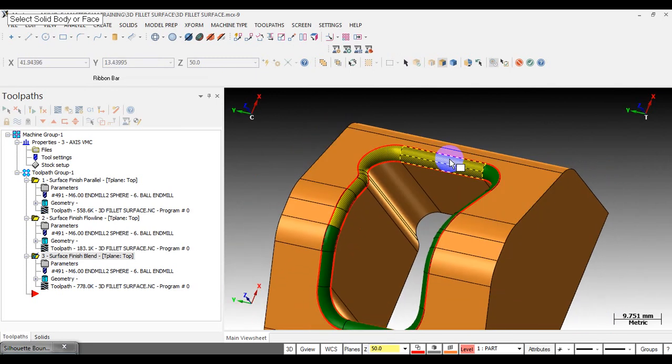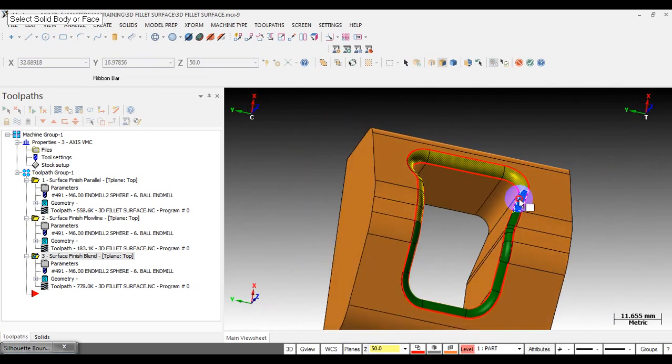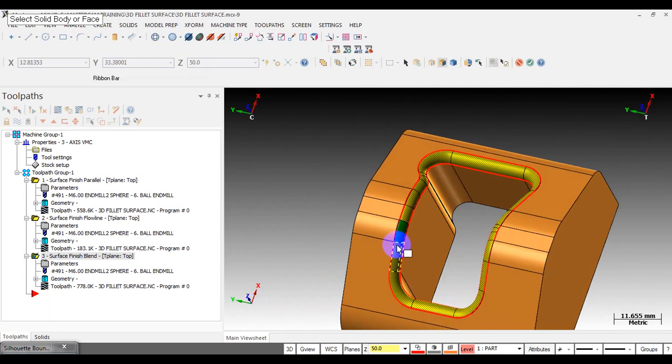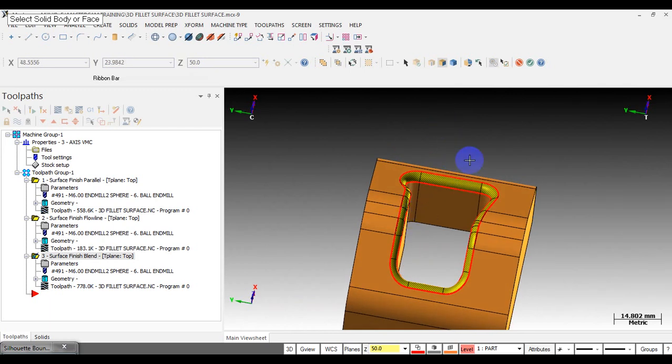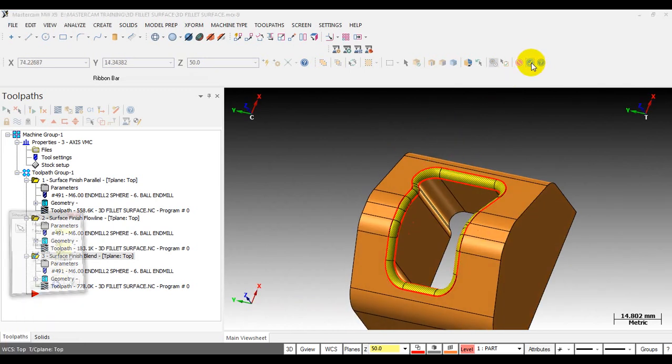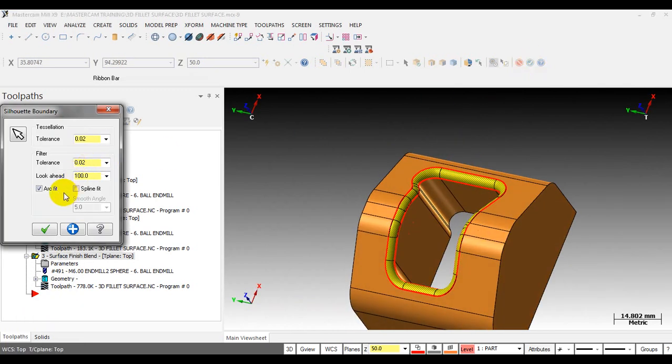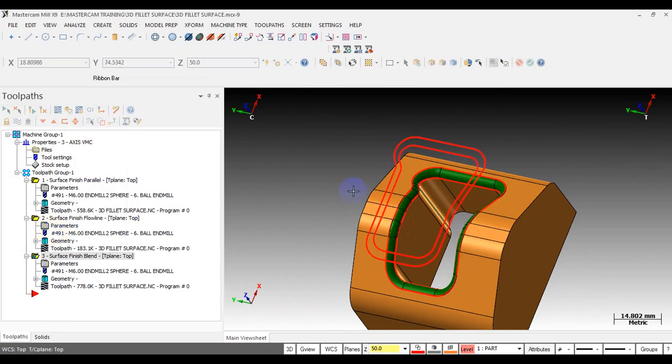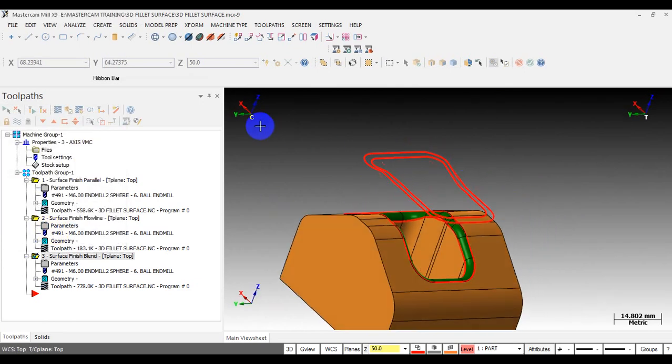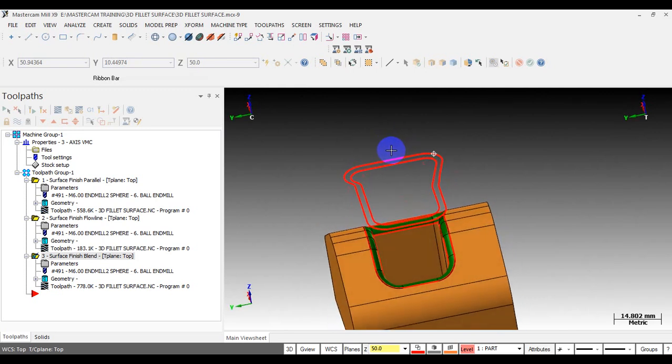You select the way you want to create the boundary chain. This function will create a 2D boundary chain. After you select it, click end selection, and you click on this. Yes, that's our trick. So what you have here is the 2D chain, outside and inside.